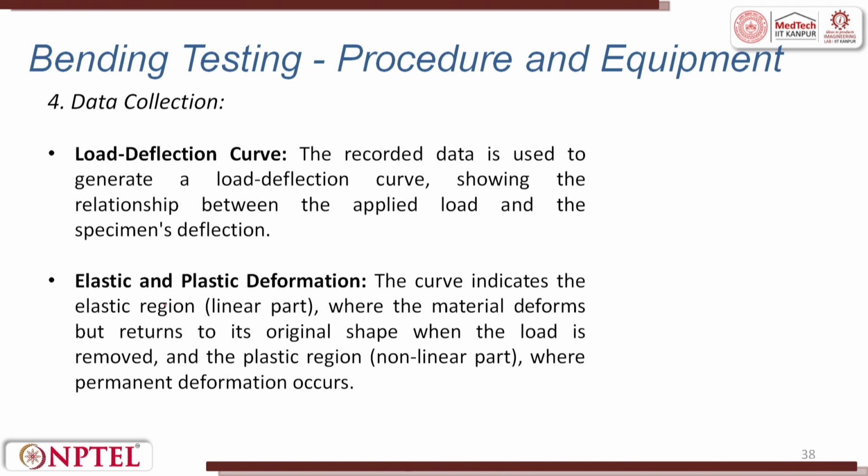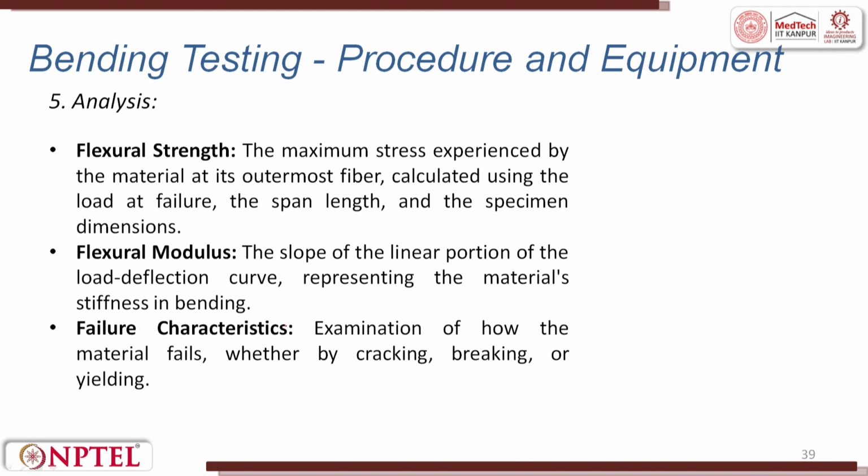Then data collection becomes the next step, where a load deflection curve is plotted. The recorded data is used to generate a load deflection curve showing the relationship between applied load and specimen's deflection. Then we get the plastic and elastic regions. The plastic region is the non-linear part, the elastic is the linear part, this you know already. Then what are the analyses that we get from this testing?